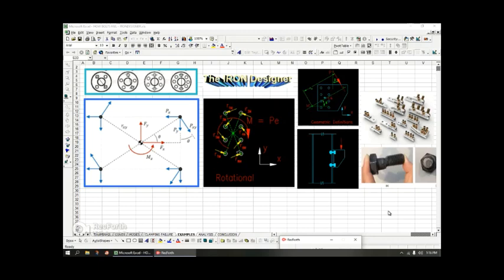If you look at the blue box, you see they have here a rectangular shaped bolt pattern with a centroid in the center with the red circular arrow, and then you have the two perpendicular forces. So you have combined loading. You have torsion on the bolt pattern from the moment, and you also have directional loads.